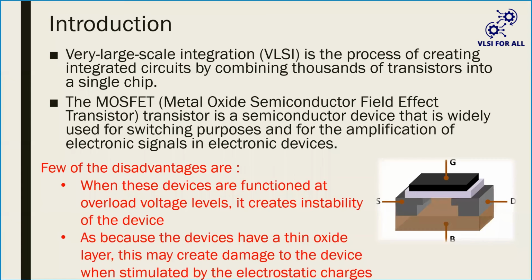Even when the inputs are stable, there is no connection from rail to rail. Hence, the static power dissipation is almost negligible. I'm not saying 0, because whenever the device is on, there might be some leakage current. There will be, obviously. So static power dissipation is not completely 0, but it is negligible.